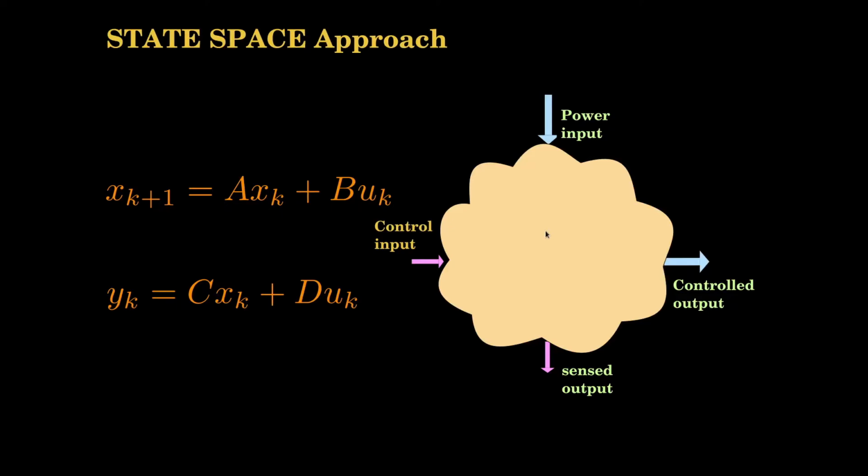And we saw how to design the controller using transfer function by the root locus method. But note that in the classical notions of control, which uses the frequency domain parameters and S-plane parameters, there are some disadvantages. It can be used only for single input, single output systems. It can be used only for linear time invariant systems. And also in the case of the transfer functions, by definition, you assume that the initial conditions are 0.